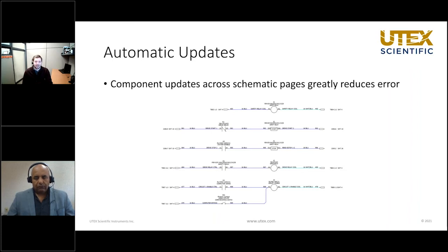It is amazing how there are relationships between manufacturer parts, symbols, wires, and connection points throughout the entire schematic, which mirror how they are on the physical system. A simple example of automatic updating is to use a relay, similar to what Talal already showed you. There are typically two parts to a relay, the coil and the contact. These can be represented by two completely different symbols and can be located in different parts of the schematic.